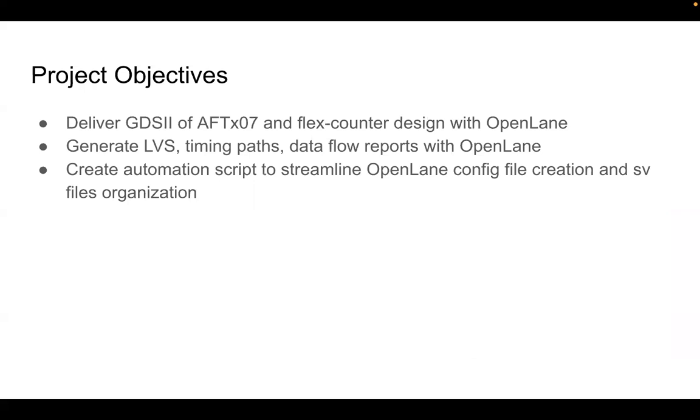In addition, not only are we generating layout, which the design flow also does, we'll also be doing timing analysis and power analysis, generating those sorts of reports with OpenLane, and then reading through those files and seeing if they're correct according to the software we have already used, with tertiary software as well. Another goal of ours is to create an automation script to run OpenLane and move configurable files around, move the SV and V files around, so that it's easier for students to use OpenLane autonomously as well.